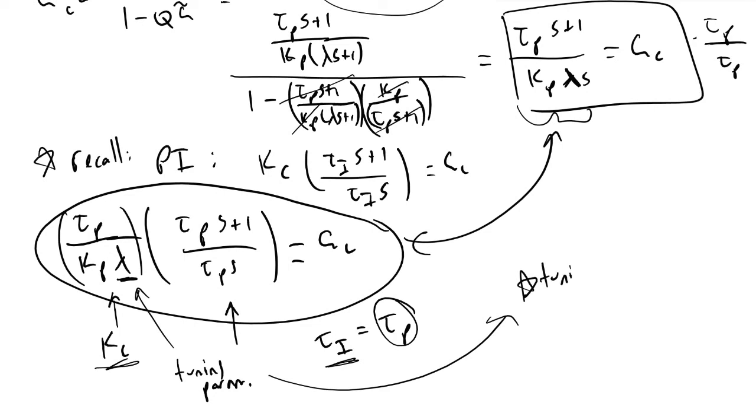So we're going to tune for performance or robustness, and you trade off between the two. You don't get all of either. That is where a process engineer will come in, and they will test out different values of lambda to see which controller transfer function meets the needs of a given project.